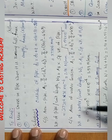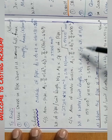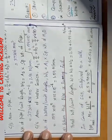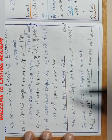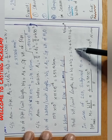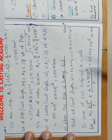Okay, weight of the water per unit length W2 equal to A2 into specific weight. So 159 into 10 power 5 into 10 power minus 6 equal to 1.59 newton per mm. So first question, when the pipe is running full, total weight per unit length W equal to W1 plus W2, so 2.91 plus 1.59 equal to 4.5 newton per mm.